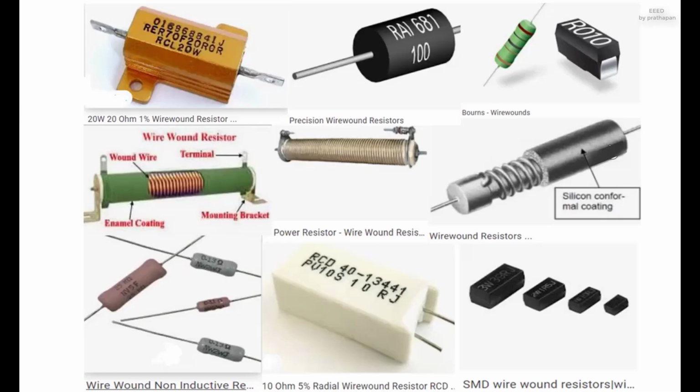Wire leads in low-power wire wound resistors are usually between 0.6 and 0.8 mm in diameter and tinned for ease of soldering. For higher power wire wound resistors, either a ceramic outer case or an aluminum outer case on top of an insulating layer is used. If the outer case is ceramic, such resistors are sometimes described as cement resistors, though they do not actually contain any traditional cement. The aluminum case types are designed to be attached to a heat sink to dissipate the heat. The rated power is dependent on being used with a suitable heat sink. Example: a 50 W power rated resistor overheats at a fraction of the power dissipation if not used with a heat sink. Large wire wound resistors may be rated for 1000 watts or more.